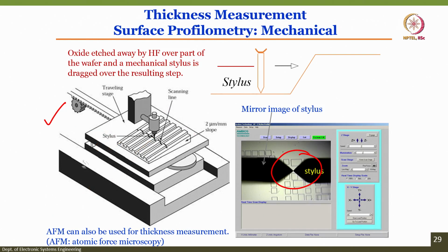So, there is a UI that comes with the profilometer through which you can measure the surface roughness or thickness of the material. Roughness or thickness, right, there is a difference: how thick the material is and how rough the material is. It can be 2 micron thick, but what is the roughness? It is 100 nanometer, 200 nanometer, 0.1 micron, 0.2 micron. If you want to know the roughness, you can measure. If you know the thickness, you measure. So, for roughness measurement, mostly atomic force microscopy is used, where I told you about the cantilever mechanism, right.